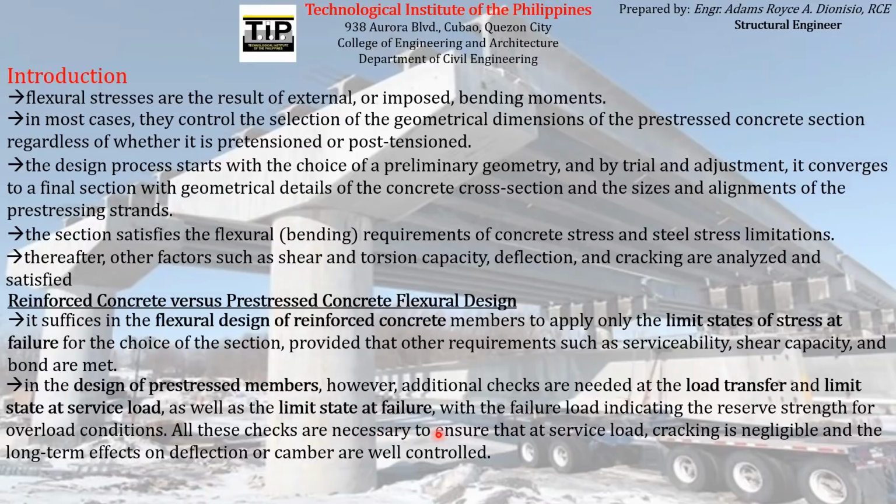All these checks are necessary to ensure that at service load, cracking is negligible and the long-term effects on deflection or camber are well controlled. So unlike the flexural design of reinforced concrete members, wherein we just check the capacity of the section at failure, for the case of pre-stressed members, we don't just check the capacity of the section at failure, but there are what we call additional checks that we usually do for the design of pre-stressed members, and